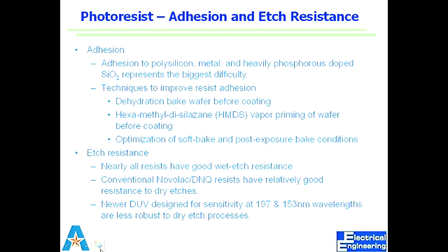Part of the reason is that the resist is a thick viscous solution, right? And if I'm doing it manually, I cannot be accurately in the center of the wafer while I'm dispensing it. So there can be weight imbalance on the chuck, and your wafer can go flying, because think about it, it's 4,000 RPM. So at stationary condition or very slow RPM, I want to apply the resist over the whole surface, make a puddle of resist.